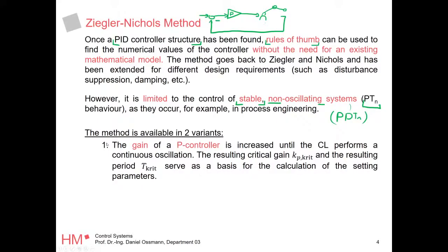And then you choose a very low value for that proportional gain, and you do the experiment. And let's say that your robot arm should move from A to B, and it moves there. If it's proportional, it will not fully move there. We know that by now. And then you turn up the gain. So it's going to get faster, and when speed comes, also oscillation comes. And you turn that gain up until it gets unstable, until the point it's just still stable. So you go to the border of stability, right? And this is called the critical gain, right?